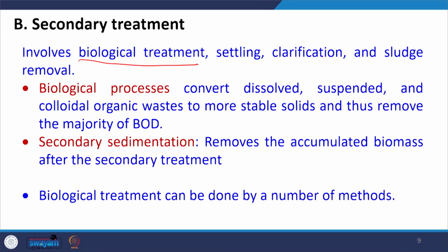And the primary focus of this course is to study this secondary treatment or biological treatment in great detail. Biological processes convert the dissolved, suspended and colloidal organic waste present in the water or wastewater to more stable solids, and thus remove the majority of BOD. Since microorganisms are used during this biological process, the microorganisms themselves grow, and thus they have to be removed also.